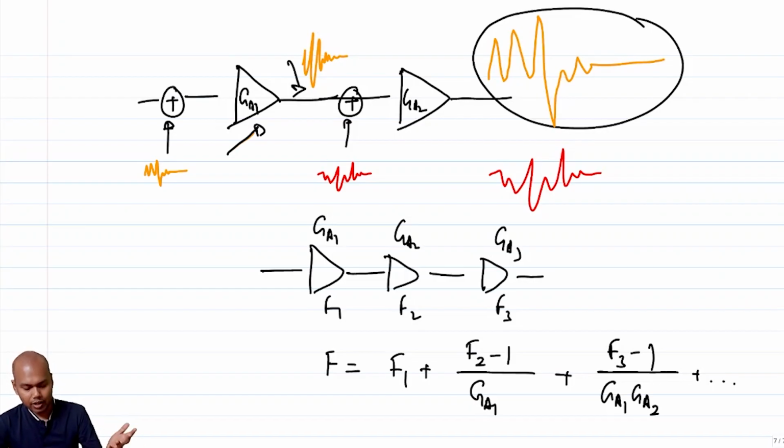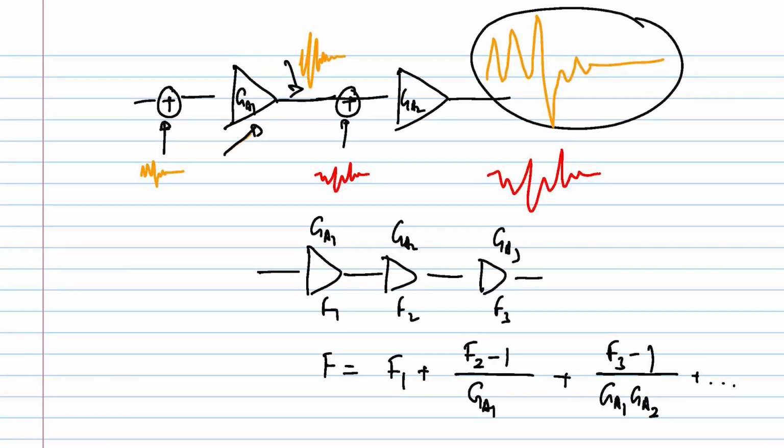right? Let's say you are evaluating a receiver and it is told to you that it has an IIP3 of minus 20 dBm and a noise figure of 3 dB. Would you consider it a good or a bad block? You should say that I do not have sufficient information, because you also have to give me the gain, right? An IIP3 of minus 20 dBm with a gain of plus 20 dB is probably not as bad. It's pretty good if I say that I have an IIP3 of 0 dBm and a gain of minus 3 dB, right? So these are some of the pitfalls that you need to be mindful of while evaluating a block, right?